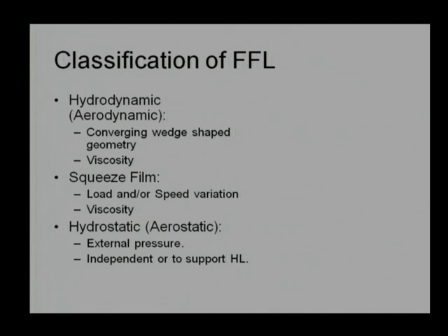As external pressure is supplied, this will be a costly mechanism compared to squeeze film action or the hydrodynamic mechanism. So, often we avoid hydrostatic or provide only a partial hydrostatic mechanism, unless there is no possibility of developing hydrodynamic action or squeeze film action.